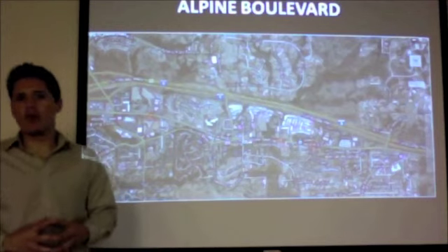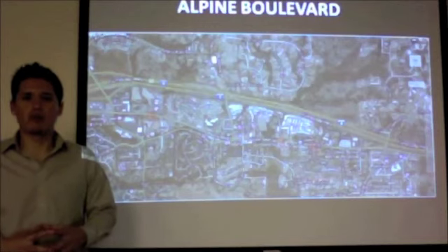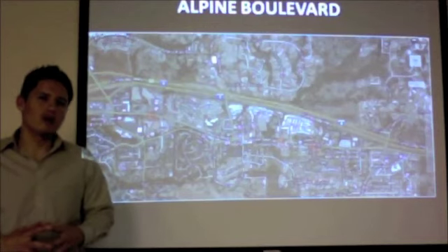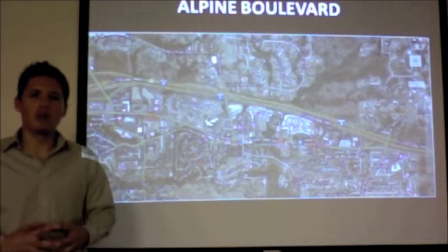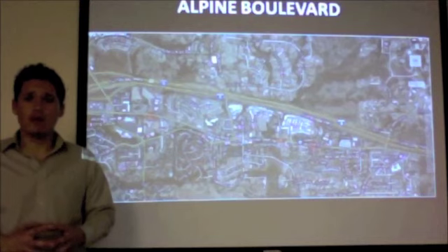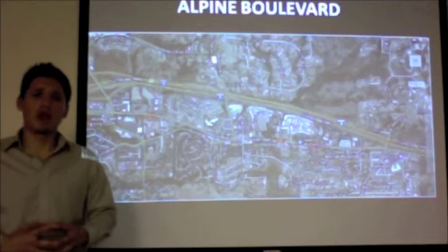The only potential area that could be affected by scour is the proposed culvert area. However, concrete rock lining is going to be placed in the channel bed underneath the culvert wash, 3 feet with the top of the rock lining to match ground elevation.